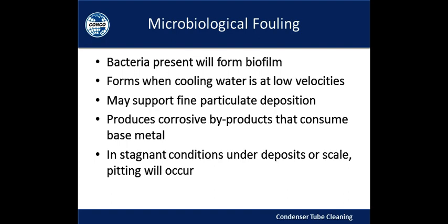So when the biofilm lies down, basically it allows the particulates to stick to it. And then that particulate deposit buildup accumulates, kind of like a snowstorm effect. That's happening on your tube surfaces. So you want to, again, remove the biofilm, and you'll have less particulates sticking to the tube surface.